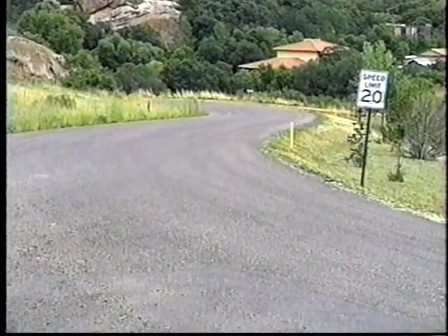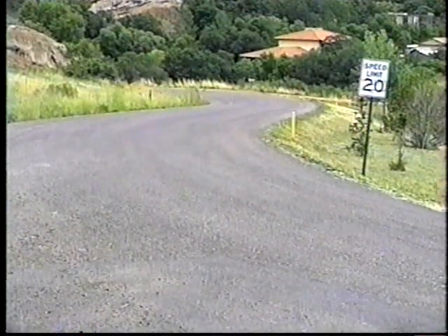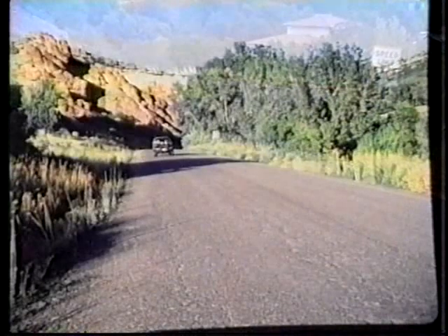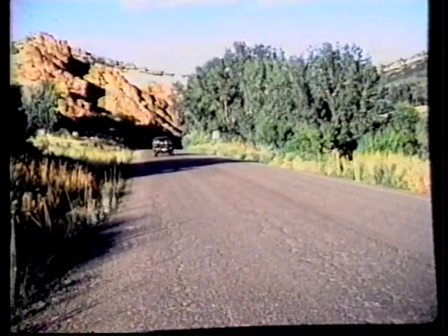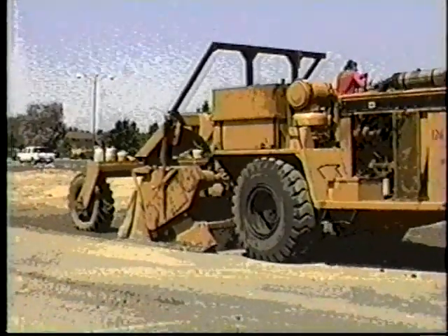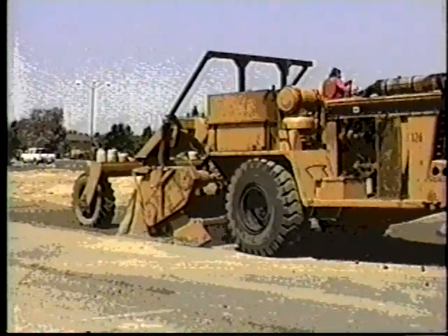course construction. Once in place, however, the compacted mixture performed so well that it was left as a pavement surface without the benefit of even a protective chip seal surface treatment. Under the severe stresses of high-altitude surface, freeze-thaw cycles, and snowplow operation, the road oil-bound asphalt millings provide a pavement that is hard to distinguish from a virgin hot mix asphalt pavement. Recycling of asphalt millings is just another application for this versatile resin-modified emulsion.